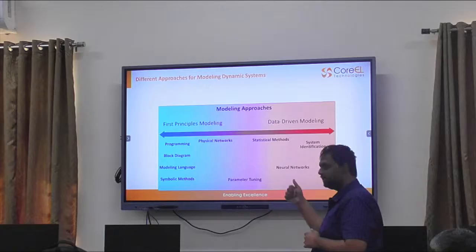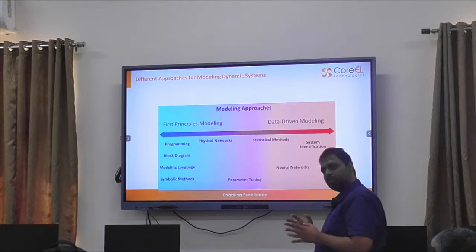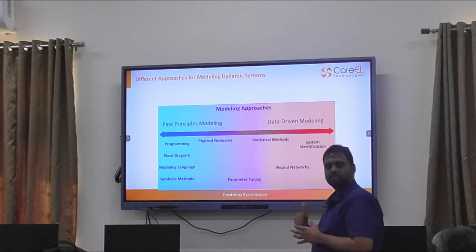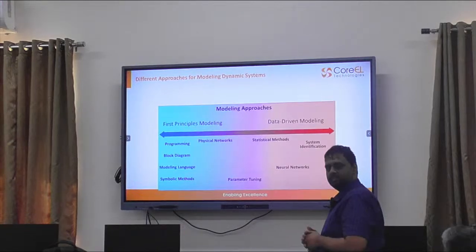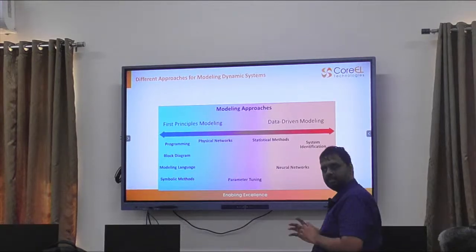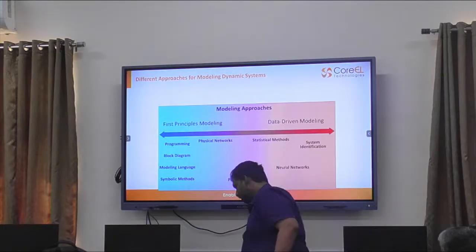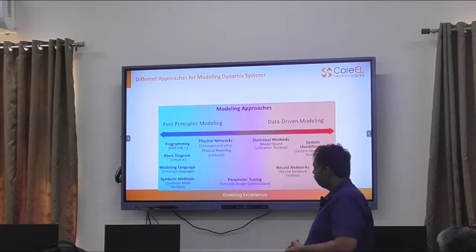There is an internal optimization library available in Simulink. So Simulink Control Design and Simulink Design Optimization, in combination of these both, we can implement our applications very easily. So we can tune the internal parameters. This is the overall broad approach, and you can see we have internal toolboxes available to handle all of these.